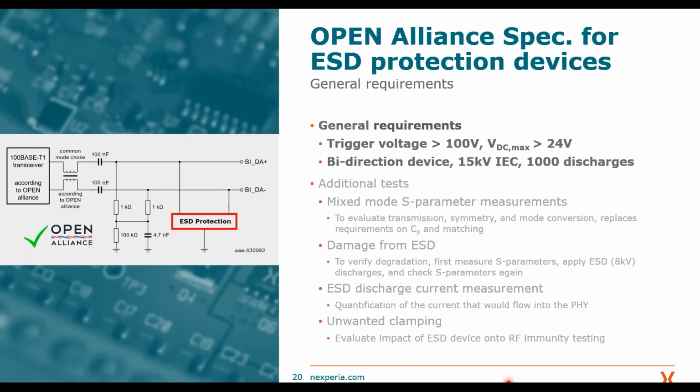So thank you, Lukas, for showing us this nice picture. Here we could clearly see what is the benefit of putting the ESD protection right in front of the connector, and this is providing by far the best ESD system level robustness. Okay, we move on to the open alliance ESD protection, and here